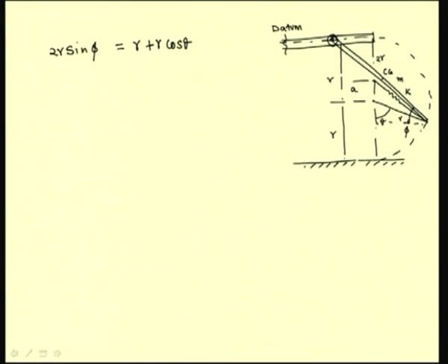because this distance, which is r cos phi, is equal to r plus this distance, which is equal to r times cos theta. And so, the CG is located at minus r plus r cos theta divided by 2, half of this distance, because this is the datum. So, this is in the negative direction. So, the CG is located at a distance of minus r plus r cos theta by 2.